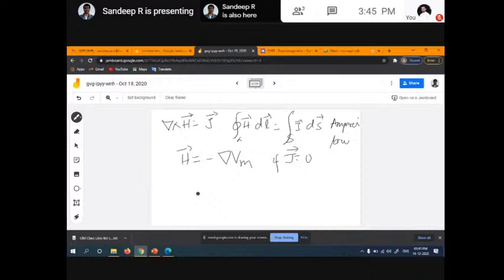We also have the magnetic vector potential, which is B is equal to del cross A, where A represents the magnetic vector potential, and A should satisfy the condition that del dot A is equal to 0. If that is the case, then we can determine the flux psi from this magnetic vector potential, which is psi equal to the closed line integral of A dot dl. This is capital psi, where L is the closed path defining the surface.